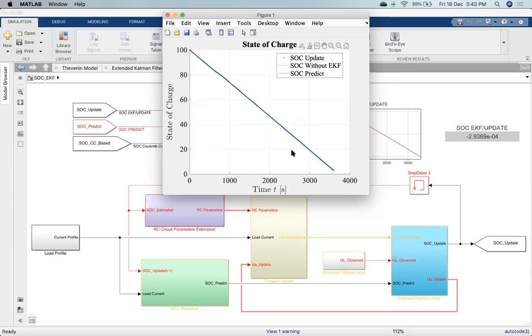If you are operating at 10C rate, the SOC has to come from 100% to 0% within 60 minutes divided by 10, which is 6 minutes, which is 360 seconds. So that's how we can validate things. I validated those things, and it's working perfectly well.